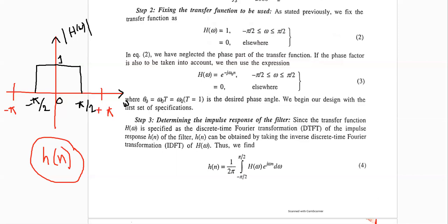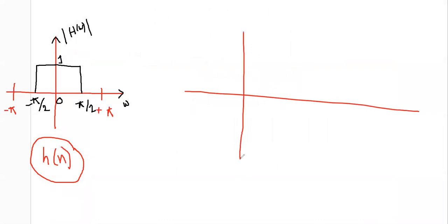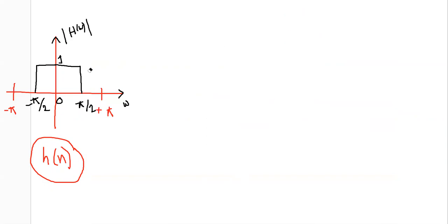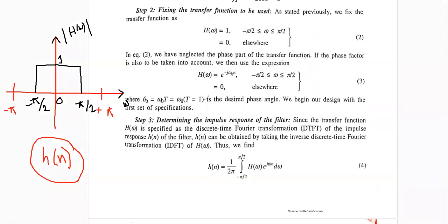In the filter domain, there is a problem. Let's give an example. In the frequency domain representation of a low pass filter, due to this sharp change, it might happen that there is a huge jump, a noise peaking jump. This kind of phenomenon makes a lot of problems, such as noise peaking, as well as a high amount of voltage in the circuit, which makes your system unstable, so much so that the circuit may even burn. That's why it is very important to consider a window.